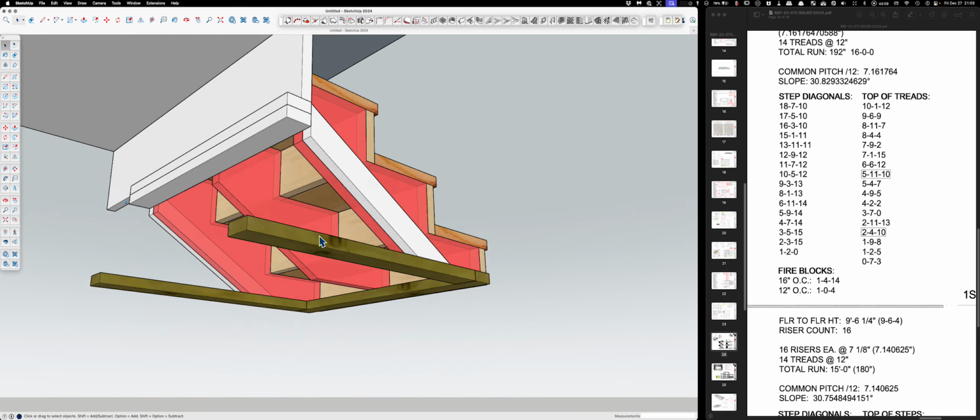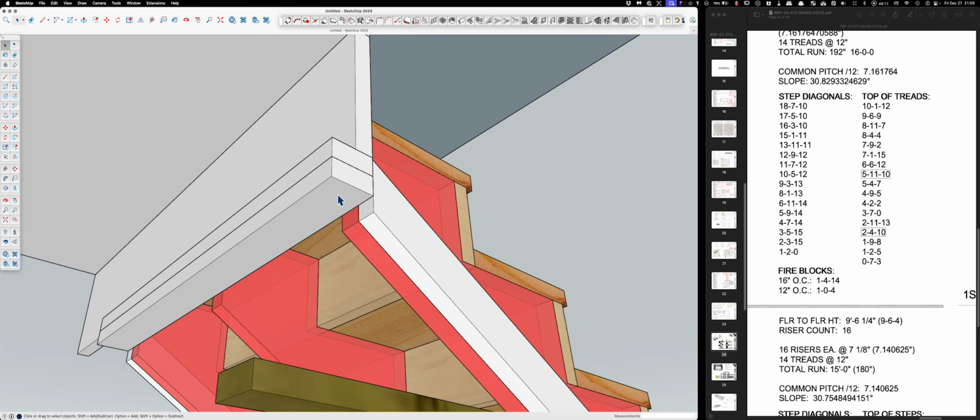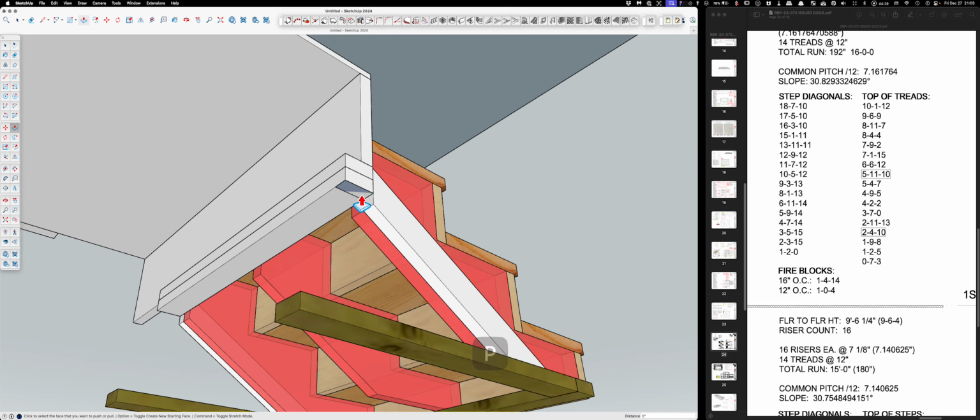So what I'm doing is I'm building a little wall here. Rectangle. So I kind of get it in where I know there's a longer side and a shorter side. And then when I look down in the bottom right, I see it's 1 7/16 by 3.5. So I'll just go 1.5, comma 3.5, enter. P. Inference down to there, 1, 2, 3. What am I doing here? G.